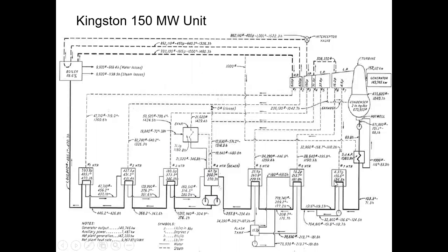So here's the lowest pressure heater, 4.37 PSI. I guess that's PSI-A, I would imagine. Yeah, absolute. And then I've got a pump, and I pump it back and merge it into the feed water flow here. So it's pumping in 32,860, it looks like, to whatever flow I have.